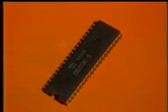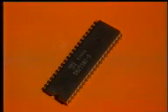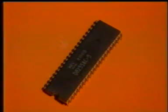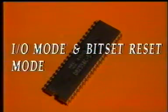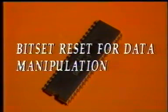Now let us review what we have learnt in this lesson. The 8255 is a peripheral interface device which can be programmed. It offers 3 8-bit ports to the user. Programming is done by writing the control word into the control word register. It offers I/O mode and bit set reset mode. Under I/O mode, simple input-output interfacing as well as handshake data transfer is possible. Bit set reset mode is good for manipulating individual bits of data.